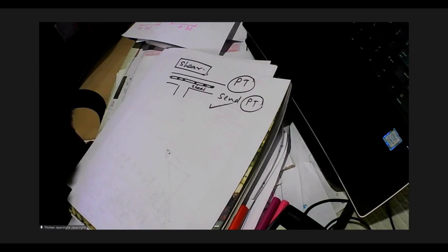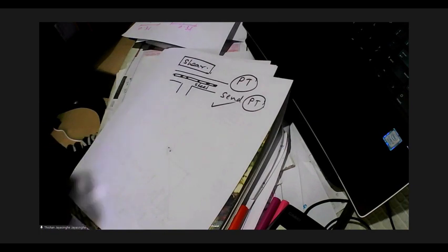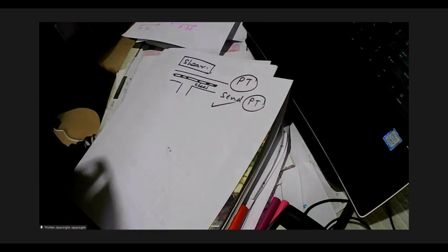So the usual practice is you'll try to understand the behavior and convert it to a one-way slab system and calculate the amount of load balance like this. Check the stresses.